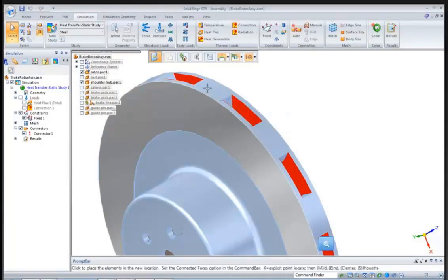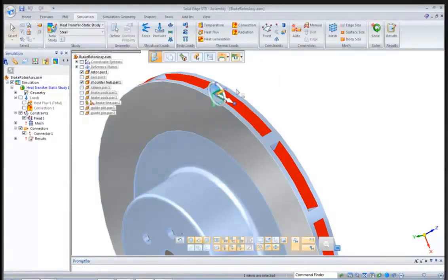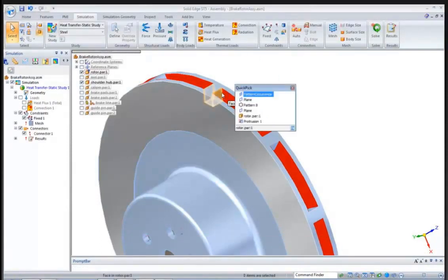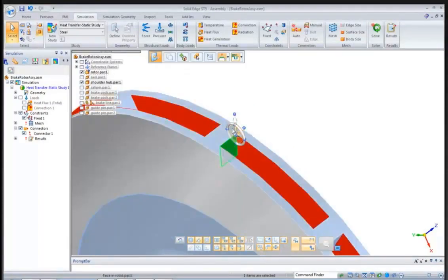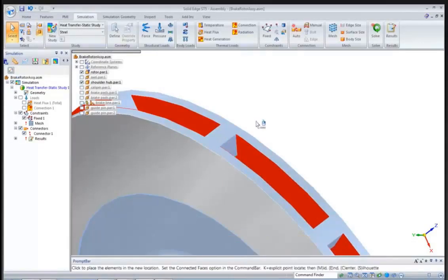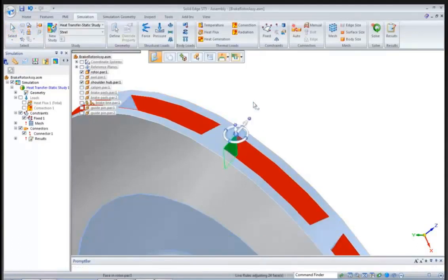I'm going to move this back using my synchronous tools, which are very handy, to, let's say, 12 millimeters. And then I also want to angle it out a little bit as well. And I want to do that about 12 degrees as well. And that looks good.